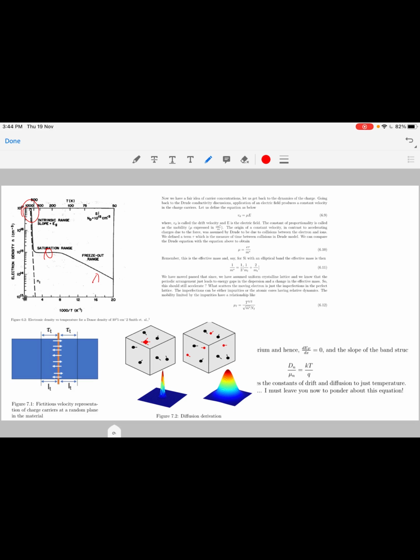And when you have such electrons in a material, then there are different kinds of transport characteristics. One is pure drift transport. As we see here, the velocity is proportional to the applied electric field. And you have diffusion transport, which, as we've seen here, is driven by a gradient in the electron concentration, or a gradient in the charge concentration. And then we derived this beautiful Einstein's equation, which relates the diffusion coefficient D with the drift coefficient mu, and they are related just by the thermal energy, that is kT by q. So we have this beautiful expression.